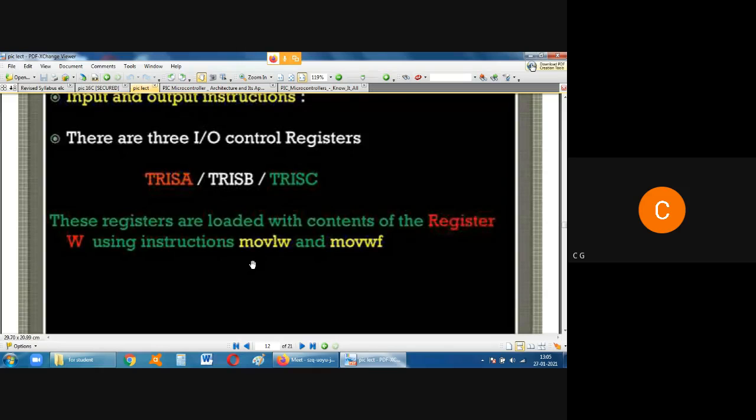So when I write 10 plus 10, I am telling that I want to add two numbers. 10 plus 10 is a decimal number. But in the machine, when it goes, it has to be decoded as 8 plus 2, okay, on the binary scale. And then it has to be added by the full adder. When it gives me a result, 20, the machine has to notify me that in a hexadecimal scale, I can have only 0 to 15, 0 to F.